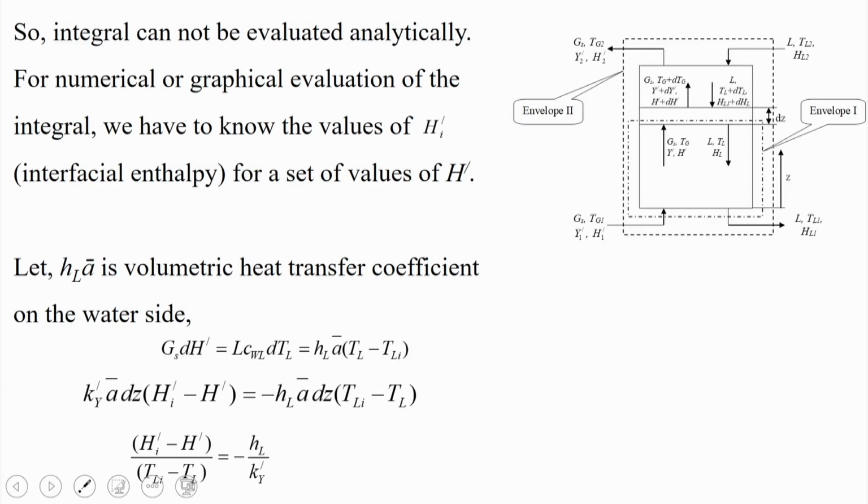So let h_L ā be the volumetric heat transfer coefficient on the water side, then G_s dH' will be equal to L C_WN dT_L, that is nothing but h_L ā (T_L - T_LI). So from there, k_y' ā dz (H_I' - H') is equal to minus h_L ā dz (T_LI - T_L).